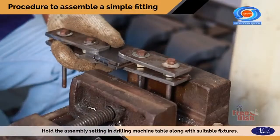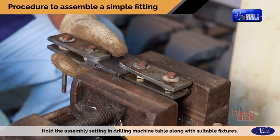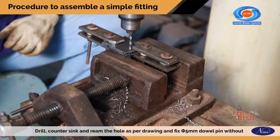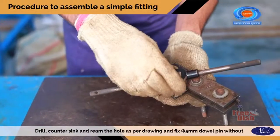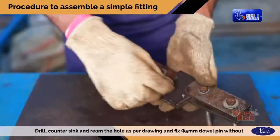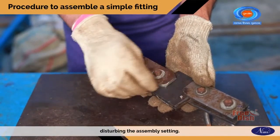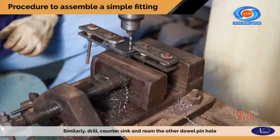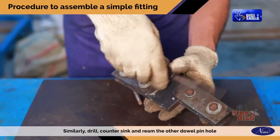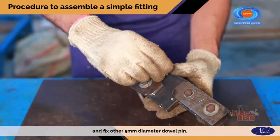Hold the assembly setting in the drilling machine table along with suitable fixtures. Drill, countersink and ream the hole as per drawing and fix diameter 5 mm dowel pin without disturbing the assembly setting. Similarly, drill, countersink and ream the other dowel pin hole without disturbing the assembly setting and fix the other 5 mm diameter dowel pin.